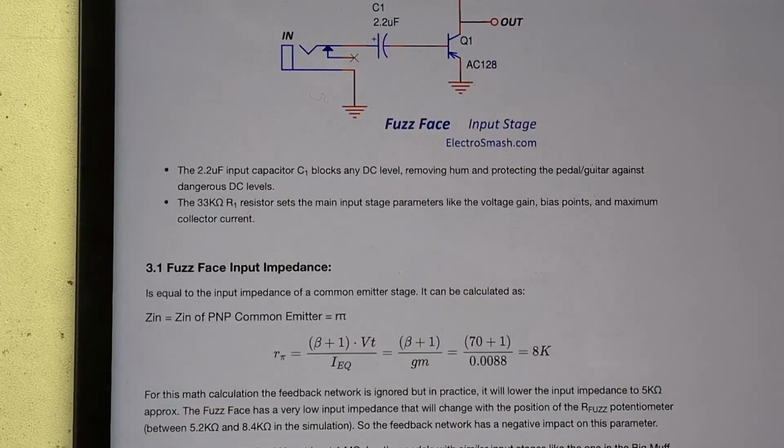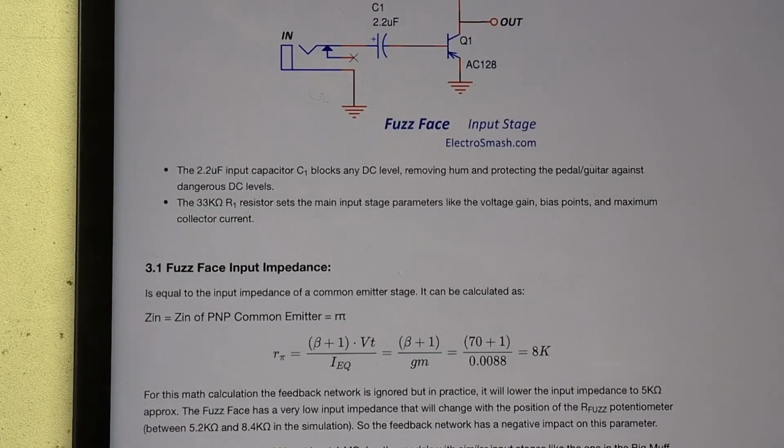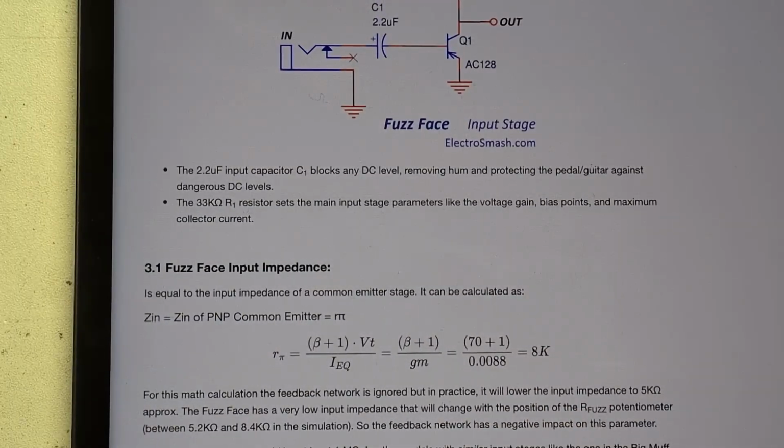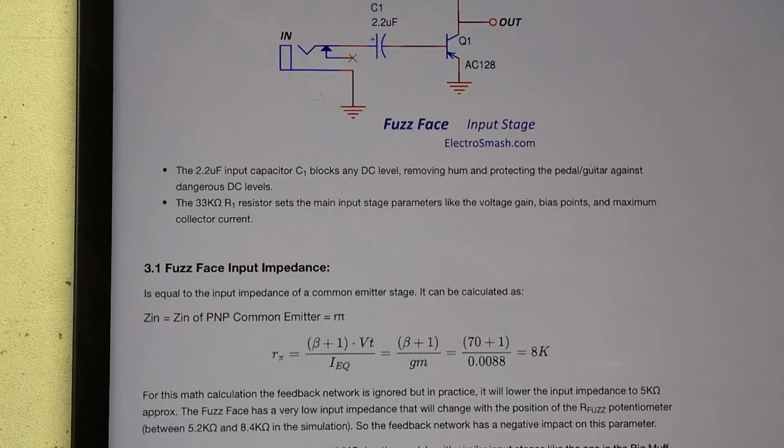And it's that interaction where you've got a guitar that, say, nominally, again, I'm going to always just use the word nominally, the resistance of the coil is, say, 10K. So you have 10K going into 8K. That's a certain voltage transfer. If you've got like 10K going into a 1 meg, that is another type of voltage transfer, and it's a better voltage transfer than this.